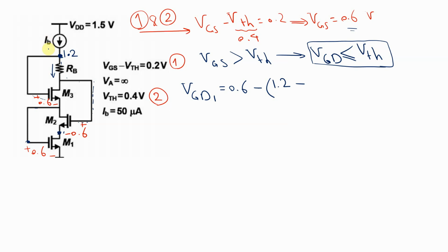This is IAB. Why is this IAB? Because the gate of the NMOS, which is this one here, has no current in it. So the voltage drop across RAB is RAB times IAB. And just move on, and here we have 0.6, because I'm using this route, the voltage drop in the value of 0.6, so minus 0.6.